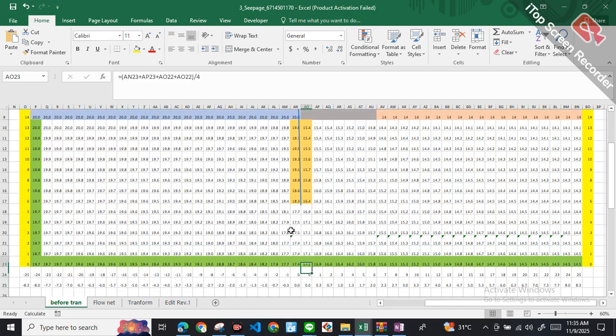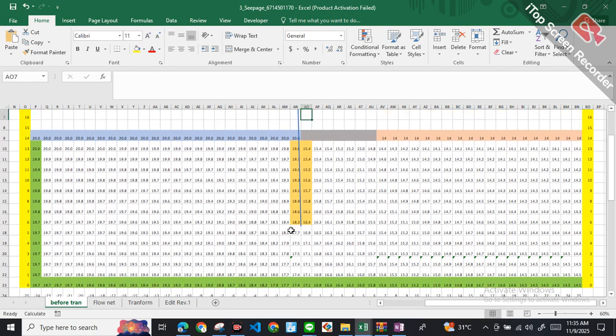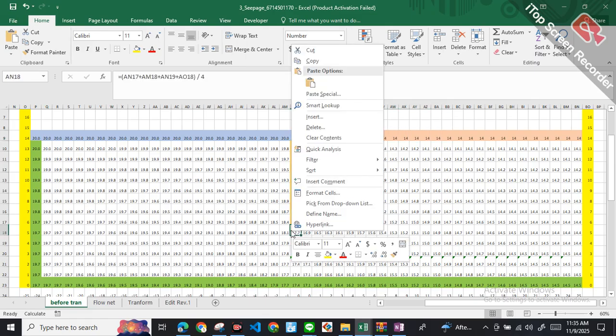Next we have, so this is basically 0, right? Okay, so this is 0. We are starting from 0 coordinate. What you can do is you can just put 0 in the middle and you can do 1, but I found this way to be easier. So the length of this impermeable layer at the top is 6 meter. Since we are beginning from 0 coordinates, so going 0, 1, 2, 3, 4, 5, 6. This is going to be 6 meter, so this is how it's represented. And we put 14 across the top for the head.